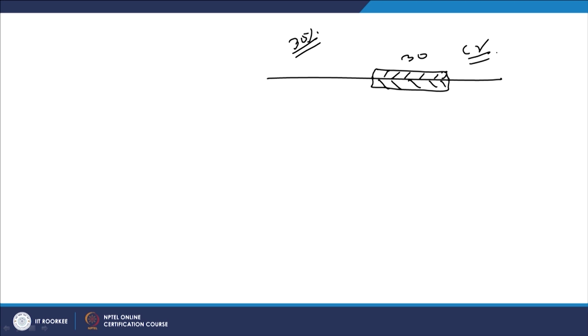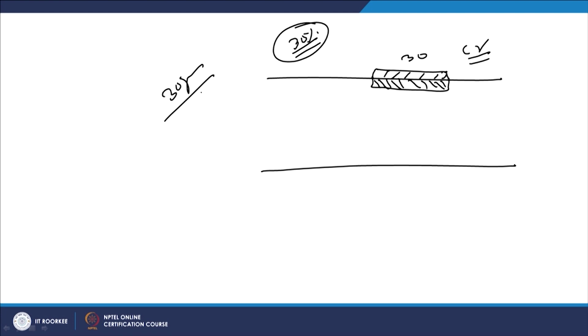If the melting is taking place up to a small depth, then the same amount of chromium which has been applied at the surface, after mixing with the base metal, will have a reduced composition. Say the alloying element applied at the surface was 30 gram, and the melting of the base metal is also taking place, say 20 gram.